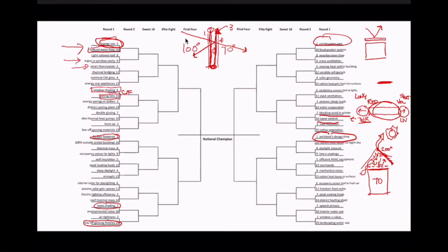But for keeping a building cool, generally a green roof is pretty good too, in part because it's not just radiant heat that we're talking about, there are conductive heat losses. So there's how good of a blanket it is on top of your building. If you're air conditioning your building and you have one roof that's concrete and another roof that's a green roof, the green roof will almost certainly have a higher R value and will lose less conductively than if you just had concrete and no insulation in it.